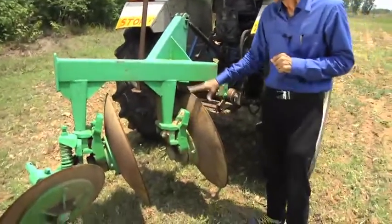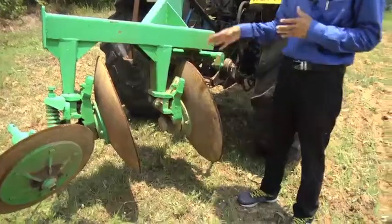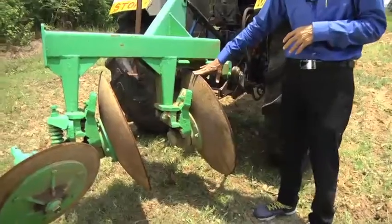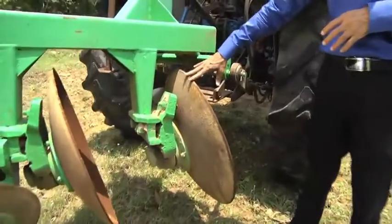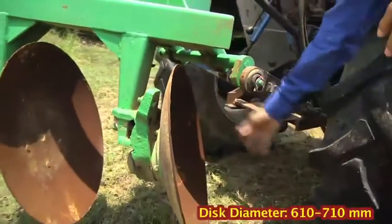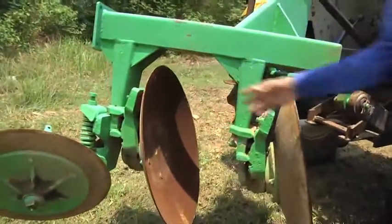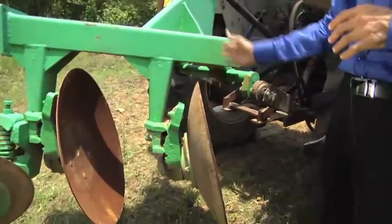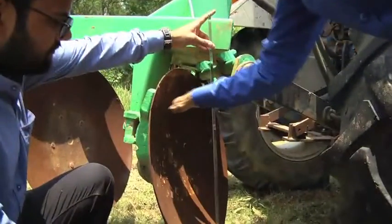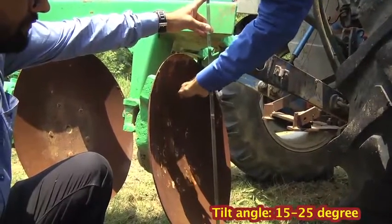Now, if you see the difference between the moldboard ploughs and this, the miniature plough which is generally in front of the moldboard plough is replaced by a concave steel disc, with a diameter varying between 610 to about 710 mm. Generally it maintains a certain position with respect to the vertical. This angle is known as the tilt angle. This helps in increasing the depth or maintaining a particular depth which we want.